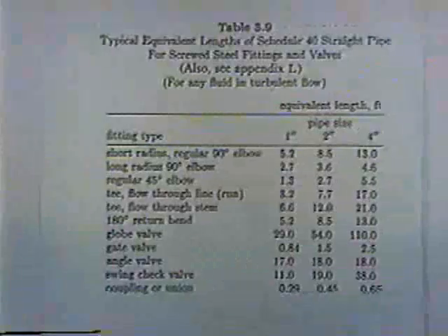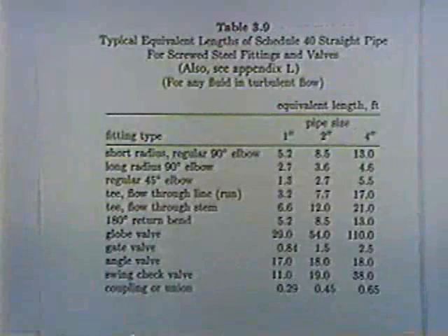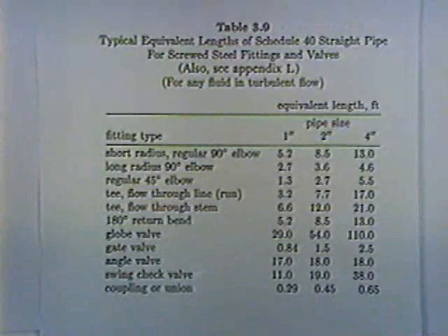And so this is just another way of expressing minor losses. And so the two ways we've looked at is the concept of an equivalent pipe, a length of pipe that gives the same head losses for a given discharge as that particular fitting or group of fittings. And then the other way is to express it as the minor loss being a minor loss coefficient times the velocity head.